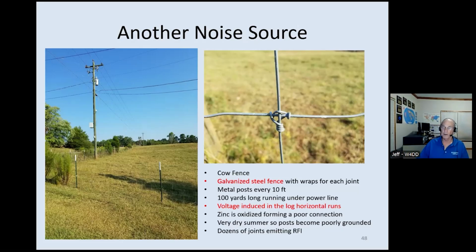The fence is making noise. I started looking at the fence, and it was a galvanized steel fence with the joints, wraps. And it turns out these wraps were making the noise. This is not soldered, it's just a wrap. And the zinc oxide is not a very good conductor.